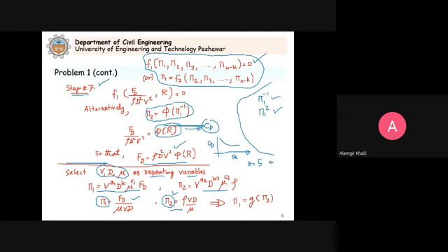And k, which we took in this problem, was equal to 3, the number of fundamental dimensions present. So n minus k, or m, was equal to 2. It means you need 2 groups to solve the problem. This is coming from the Buckingham pi theorem, so this is fixed.